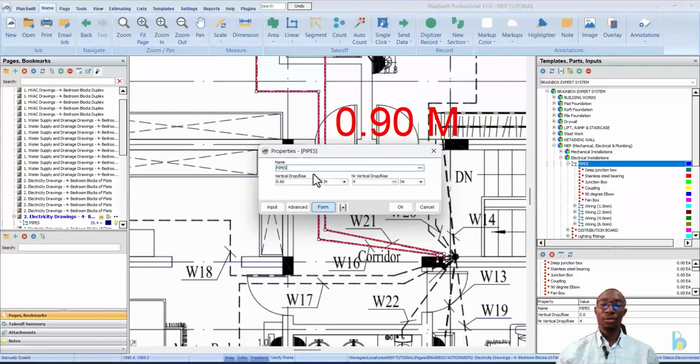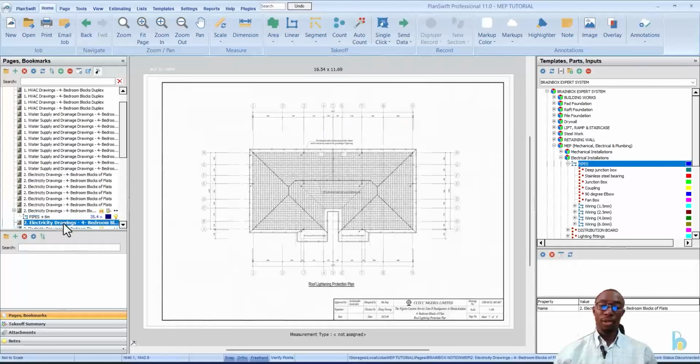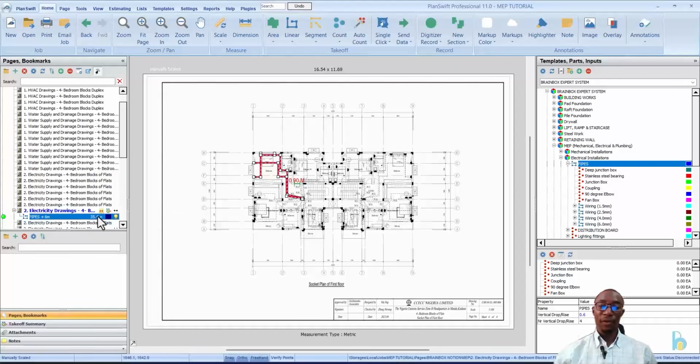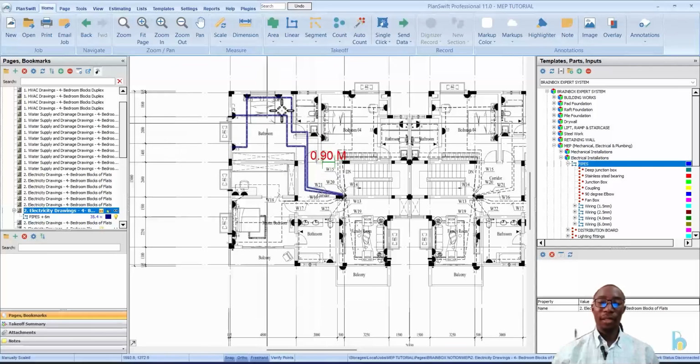So this is going to be whatever we have here plus 6 meter. So when I am adding up my BOQ, I'm going to take note of this, whatever length I have, plus 6 meter. So this is for this. So basically, this is how you are going to apply the same method to all the rooms here.